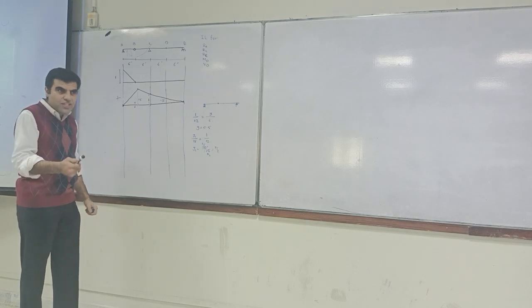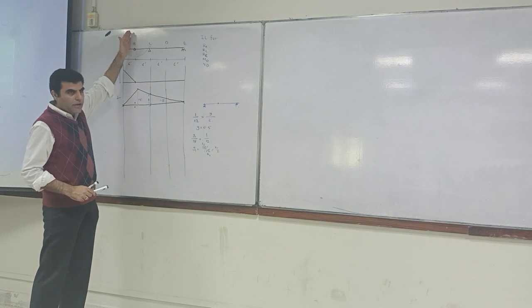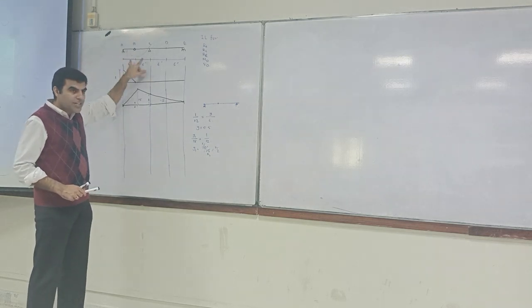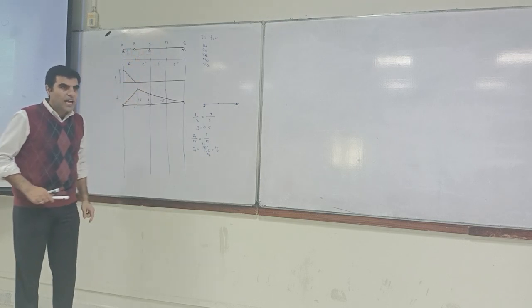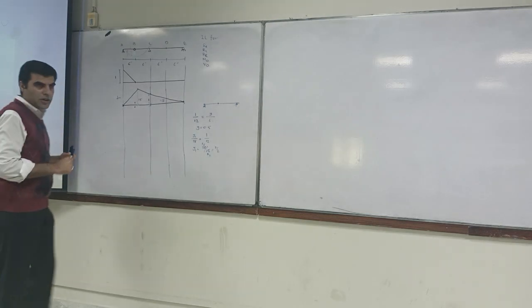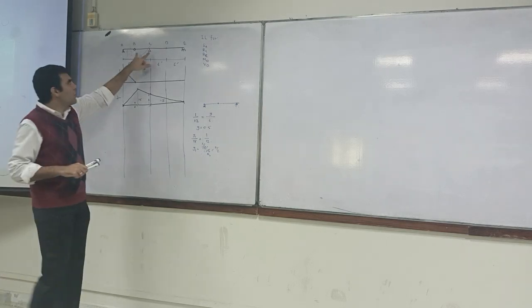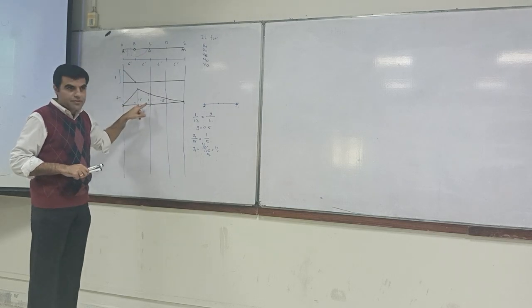If you want to do a further check, as I told you, you can place the load over here, find the reactions, then place the load over here, find the reactions, place the load over here, find the reactions, and you will see this. That's what's going to be your assignment: you have to do it by first principle and the Muller-Breslau principle. Okay, so is that okay?